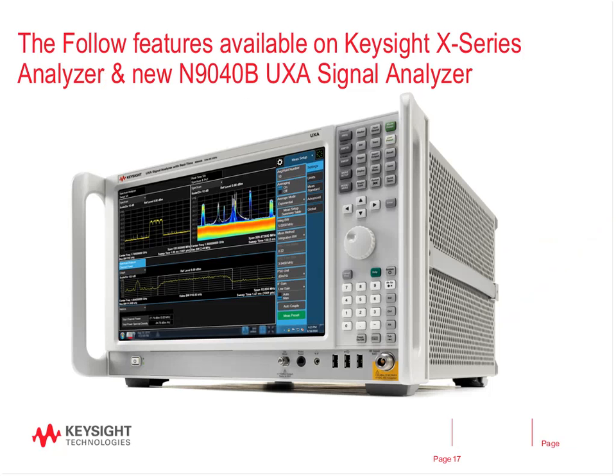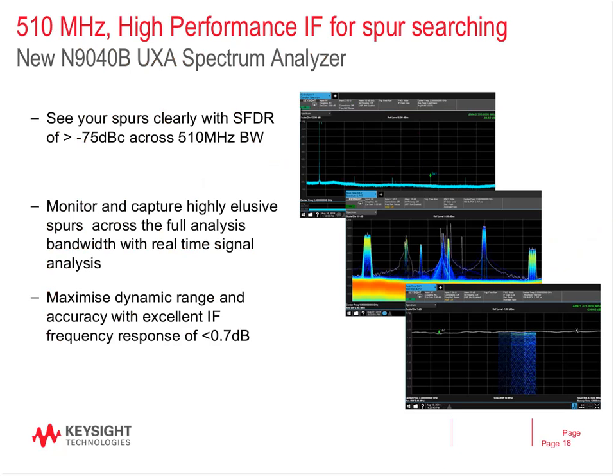And so in the next few slides, what I'm going to be covering is available in our new UXA spectrum analyzer, okay? So if you want to find out more, that's the product you want to look for. This particular instrument has a brand new IF section. It has an instantaneous bandwidth of 510 megahertz with full IF processing. And there are 3 areas which we'll cover: dynamic range, the ability to real-time process the signal, and excellent flatness for good measurement error budget management.